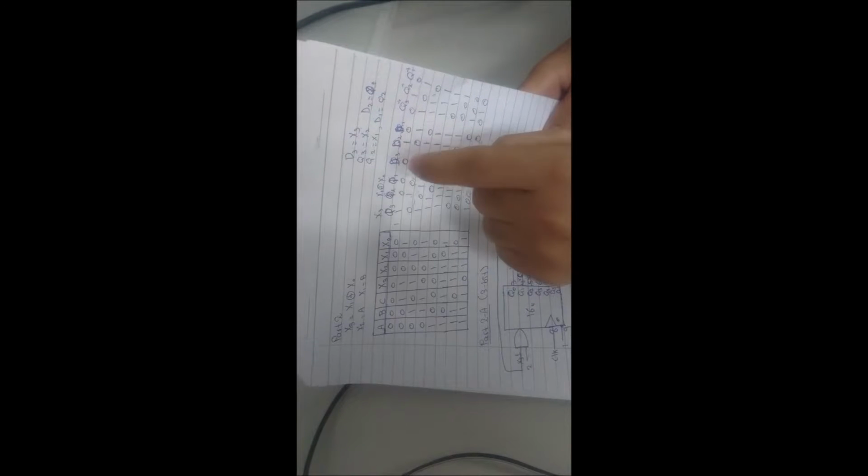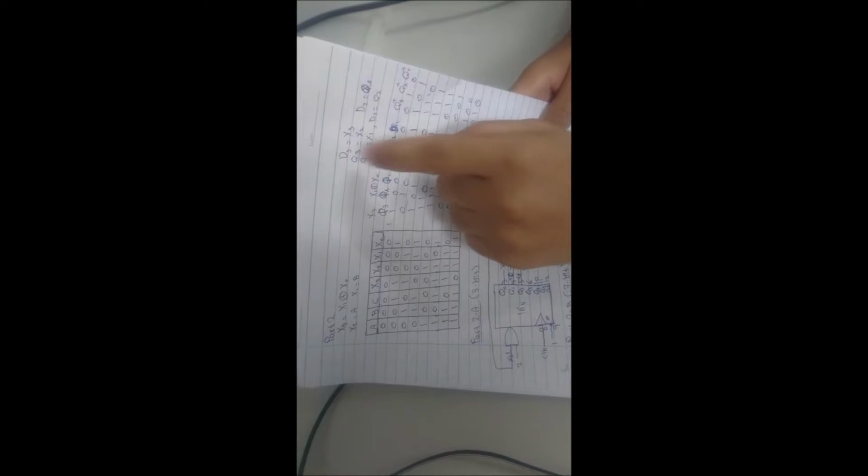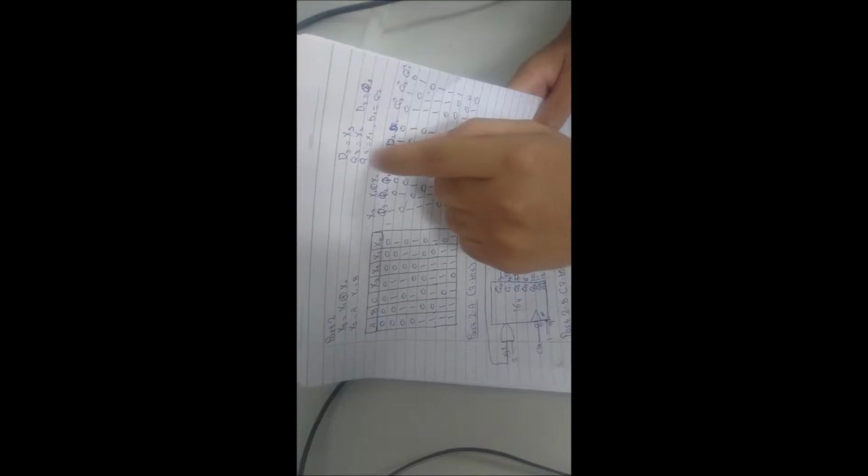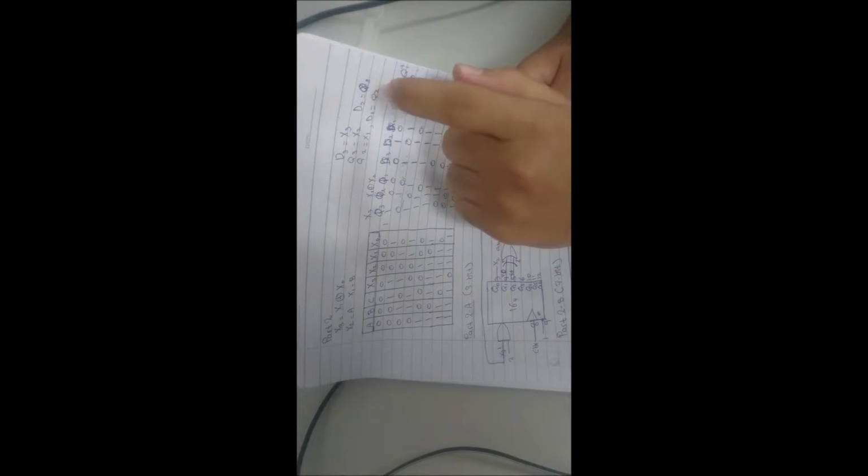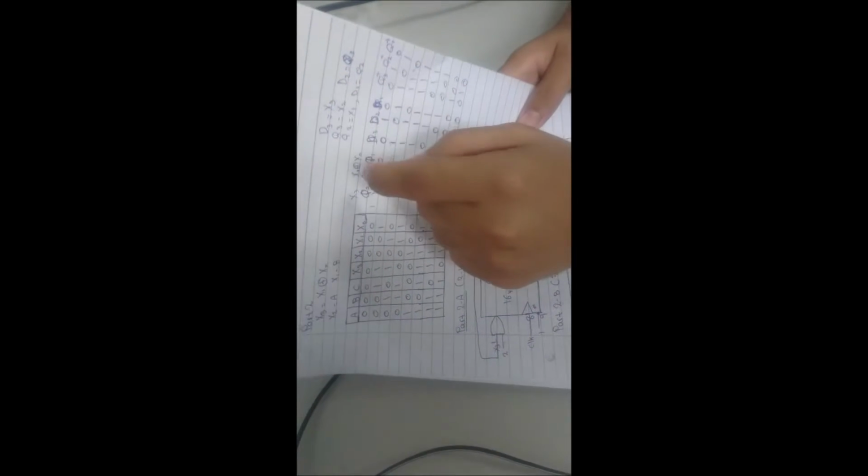My name is Mohammed and I will explain part 2 in lab 4. So this is our state diagram. We got this state diagram from our truth table. This is the equation that we came up with in order to get the truth table. For the D flip-flop, the answer for the next state will depend on the D flip-flop. We determine that D3 is equal to X3, Q3 equal to X2, Q2 equal to X1, D2 equal to Q3, D1 equal to Q2. So we determine the first state is 100 based on the timing diagram.